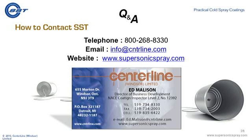So what I'm hearing here, Mark, is maybe a customer considering using cold spray as an intermediate coat. That's a good idea because cold spray has very good properties. You can move along at a fairly productive rate, and then you can thermal spray or plasma spray a material over the cold spray surface. I guess the rules are the same, so long as you treat that coating as if it were a substrate. In other words, is it well adhered to the original substrate? Is it clean? Is it free of oxides and contamination?